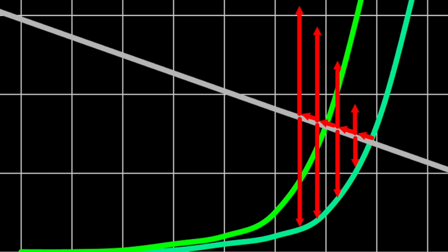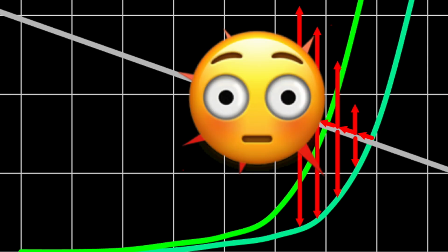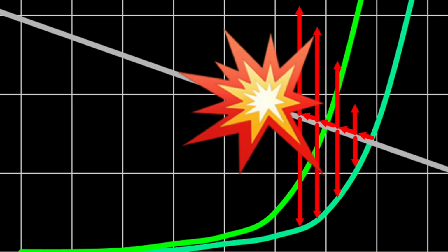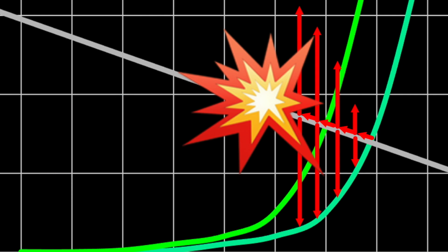Eventually, the full current intended for 2 is flowing through one LED, which is destroyed from that. Next, the full current flows through the second LED, destroying it too. So, if you want to operate semiconductors at their performance limits in parallel, you have to keep an eye on tolerances and temperatures. The graphical method can be very helpful assessing that problem.